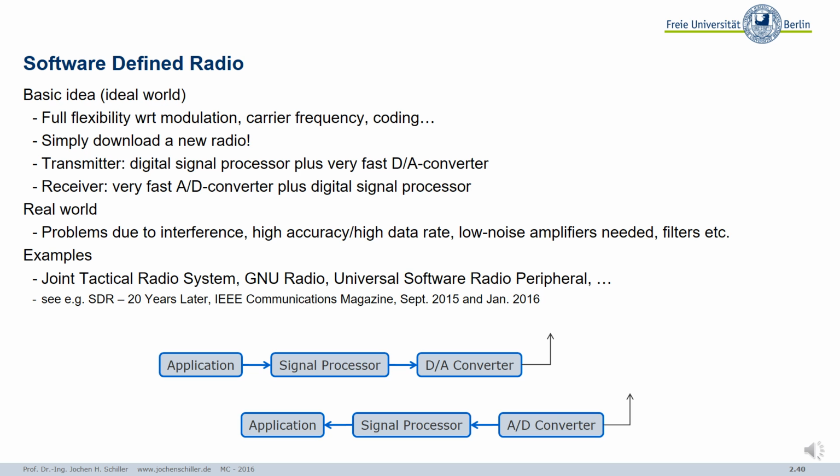Okay, and now something that also fits quite nicely here. You saw we can play with many parameters, like phase, like amplitude. We can perform spreading. We saw a digital way of spreading, this direct sequence spread spectrum. And many years ago, that simple idea popped up that said, okay, why can't we create the complete real signal we transmit over the air already in a computer, in a full digital way?